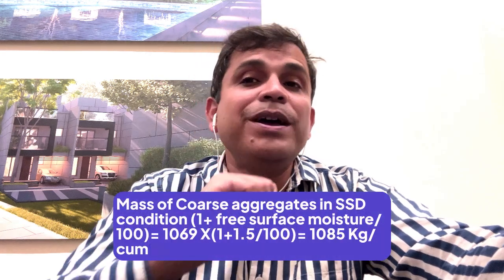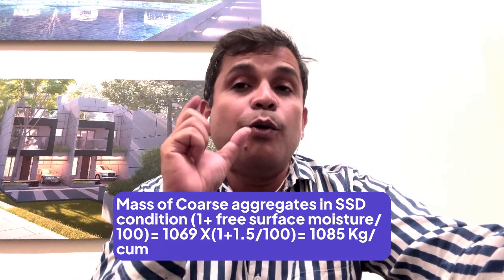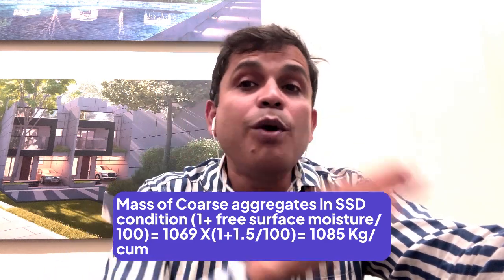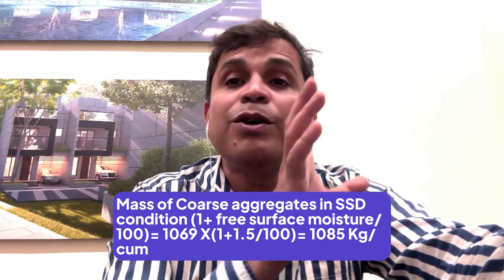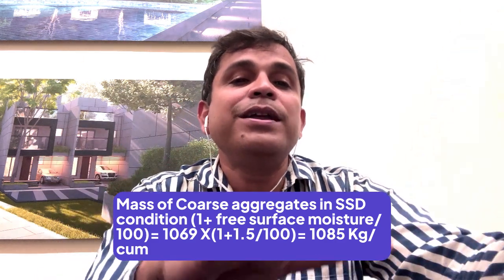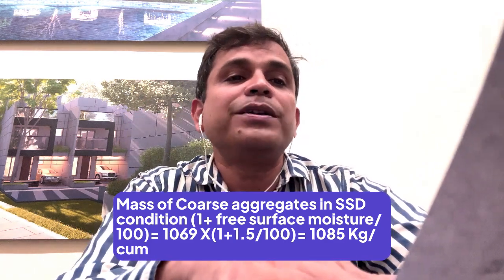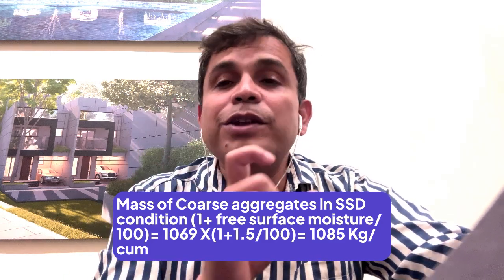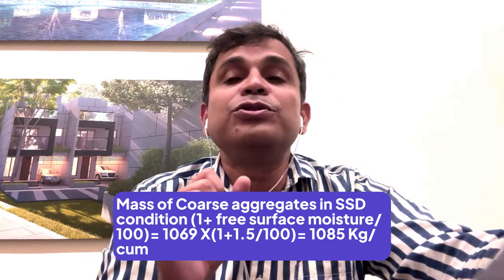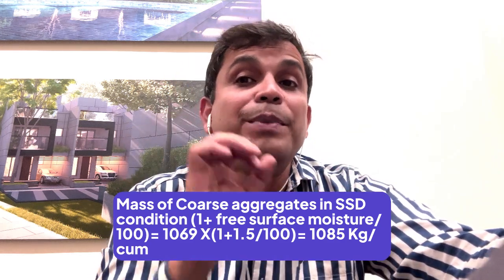For the coarse aggregate, my quantity is 1069, and the moisture it can retain is 1.5 percent. Now, if I take only 1069, we will get a lower amount of the coarse aggregate. So again 1.5% we need to add, and if we add that, it comes to 1085 kgs. So if we take 1085 kgs of coarse aggregate, then we will get 1069 kgs of coarse aggregate as per our mix proportion of the concrete.